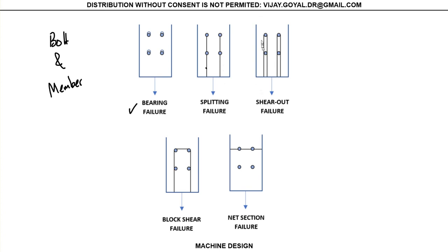This is a shear out. Basically, it doesn't have the capability, so this basically pulls all the way out and comes out. Okay, so the failure happens like this. It just keeps moving in this direction. So if I keep moving, this will keep moving in this direction. So that's how the failure occurs. Here, this is a block failure where when you pull, this whole thing comes apart as a block.